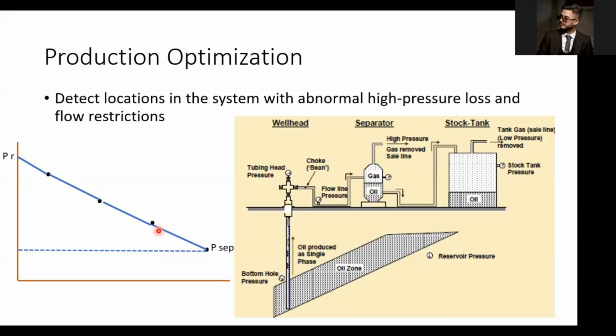Then there are some components that typically happen where we have, in the tubing or flow line, some wax, or debris, sand debris in the flow line over time. That will be seen as increasing delta P in the flow line area over time. So in this case, we have to monitor and look at this curve over time to see if we have increasing delta P. It might be caused by debris or wax or any such debris in the top facilities.